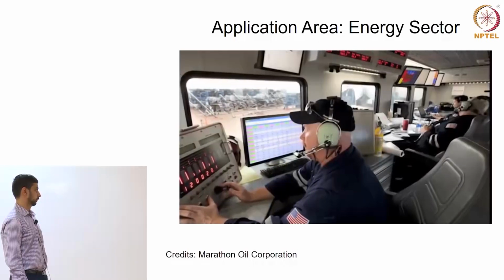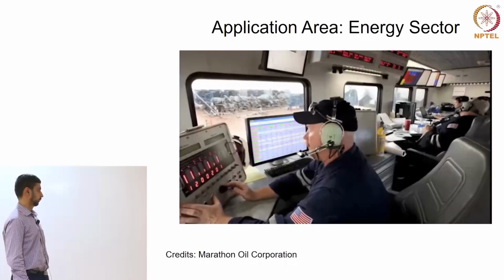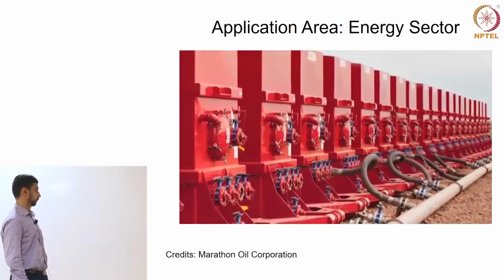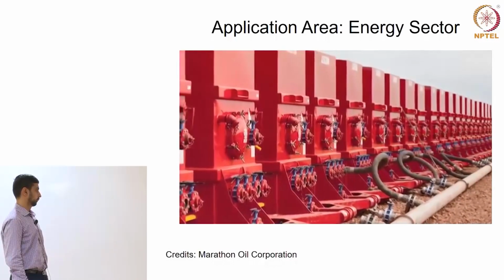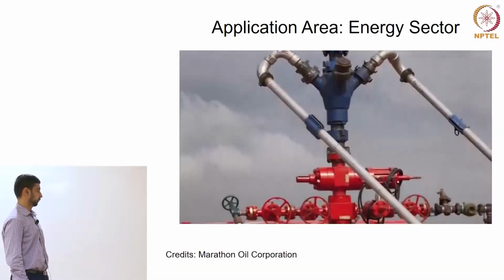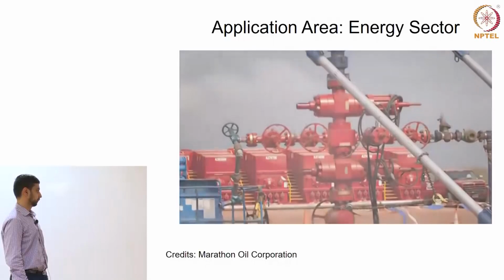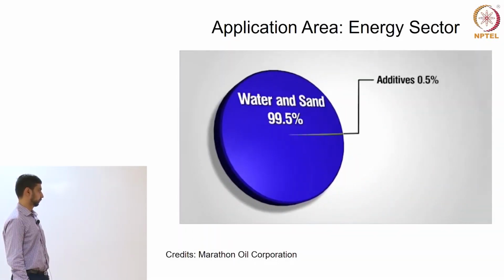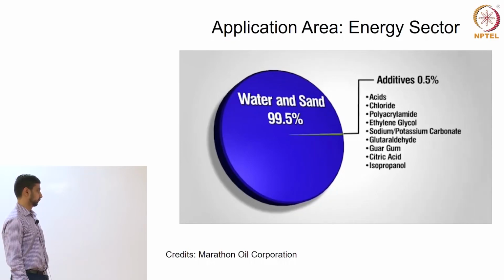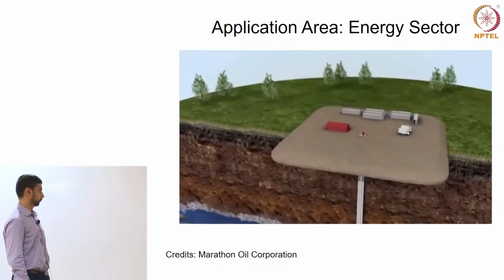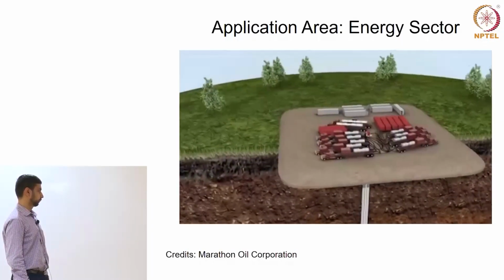The process consists of pumping a mixture of mostly water and sand, plus a few chemicals, under controlled conditions into deep underground reservoir formations. The chemicals are generally for lubrication, to keep bacteria from forming, and help carry the sand. These chemicals typically range in concentrations from 0.1 to 0.5% by volume, and help to improve the performance of the stimulation. This stimulation fluid is sent to trucks that pump the fluid into the wellbore and out through the perforations that were noted earlier.